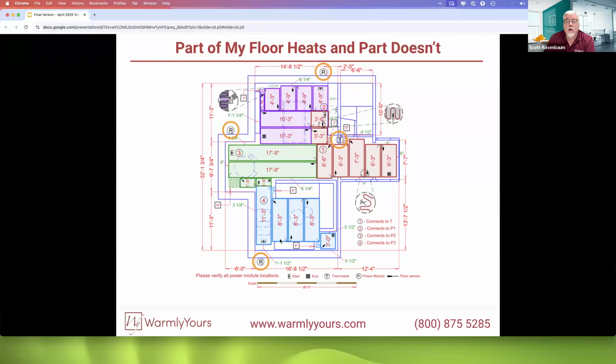So that's why all of our testing starts with ohms, ohms, ohms, over and over again, not a continuity checker. That's not the same thing. You want a digital ohm meter, and that's always the first step of troubleshooting, is to use that.